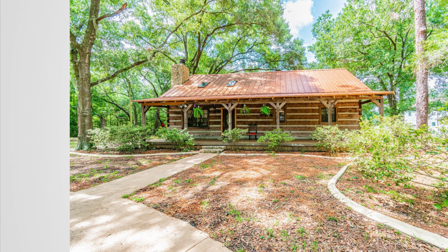This home is in Tampa, Florida, so obviously in a subtropical environment where we have high humidity and a lot of moisture, termites can be a big issue. But think about the types of termites that can be in a certain area as well. Here in this area, we have subterranean, Formosan subterranean, and drywood. That adds a whole new twist to inspecting for termites, as opposed to inspecting somewhere like Ohio, where you do have fairly common subterranean, but you would never see a drywood termite.